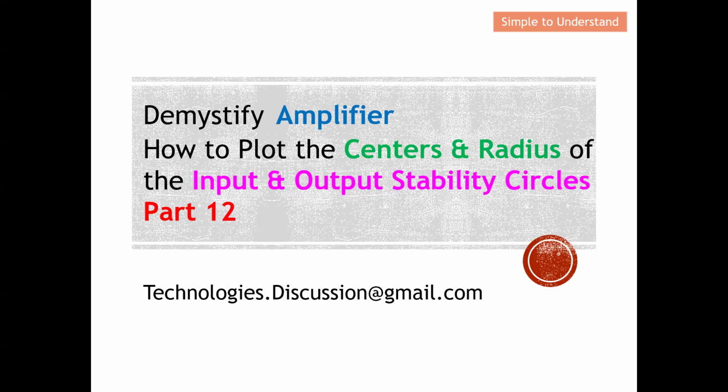Before we come to the plotting of the stability circle, let's understand when we need to plot it. For example, if the amplifier is unconditionally stable, which means that the amplifier doesn't need any specific condition to be stable, then we don't need to plot this stability circle because the amplifier is always stable. The reason that we plot this stability circle is when the amplifier is conditionally stable, which means that we need to specify which condition the amplifier will be stable under.